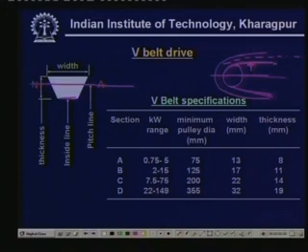Okay. So, this is an inside line and this is the pitch line. These two parameters are very important because while using the equations of belt drive, whatever the pulley diameter or the belt length L, all what we compute are based on this pitch line, meaning the values you are getting or using are all pitch line values.